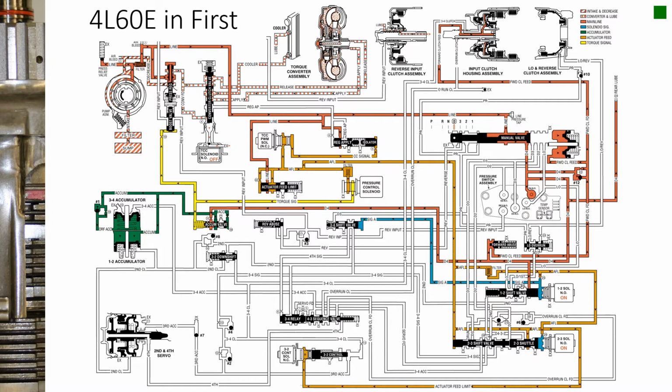This is the complete hydraulic schematic for first gear. The only thing that really happens when we shift into drive, you can see the pin is over the drive passage there, is now line pressure has the ability of coming in and it enters this D4 clutch circuit.